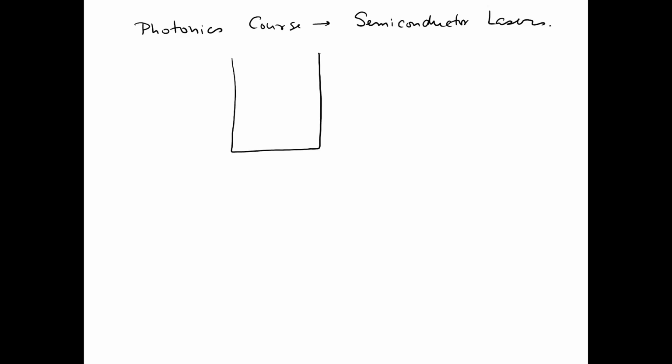These quantum wells you're going to see again in your photonics course when you do optical communication. When you look at semiconductor lasers, these quantum wells play a very important role in semiconductor lasers. It's because of these quantum wells that semiconductor lasers have become as efficient as they are today. And what happens in semiconductor lasers is you make a quantum well in the conduction band.